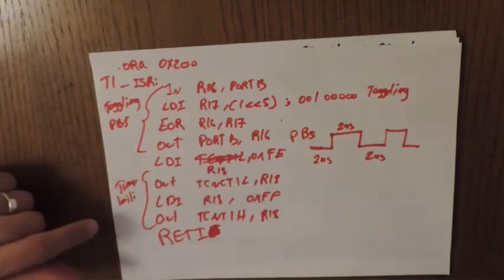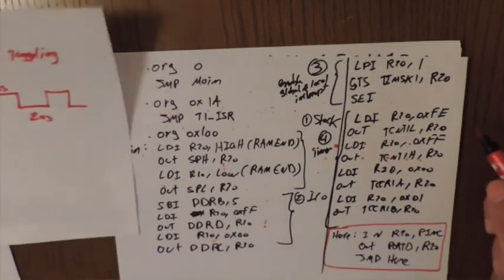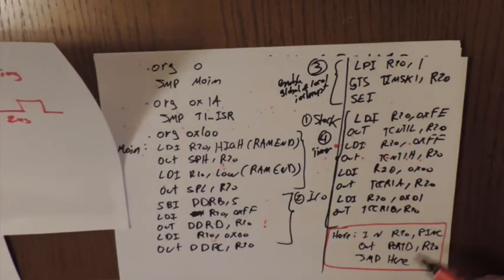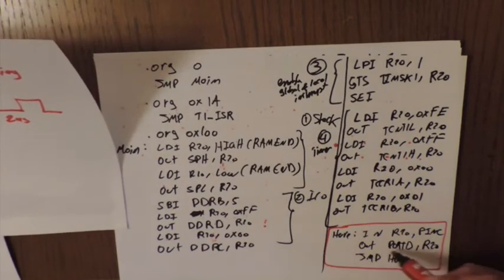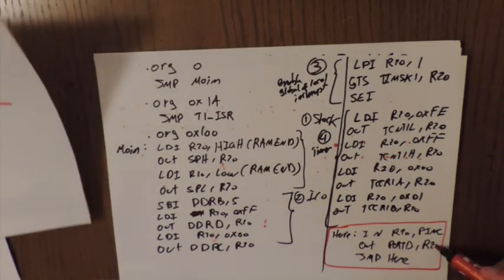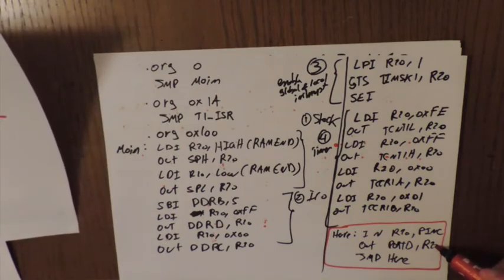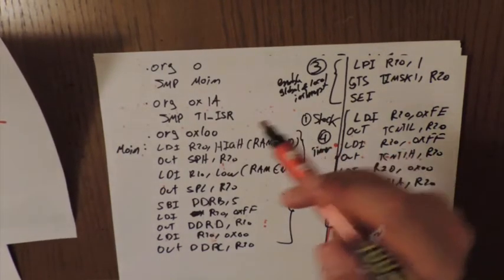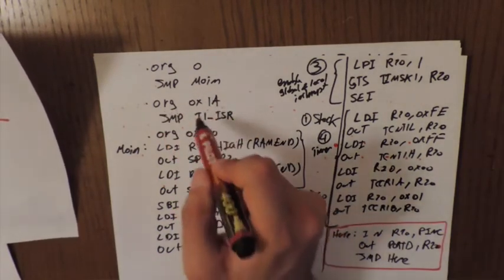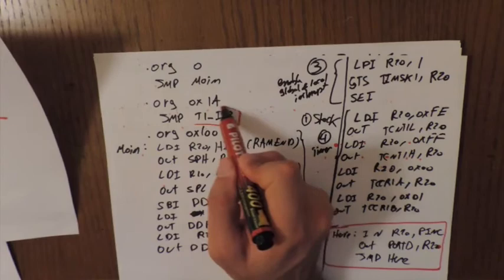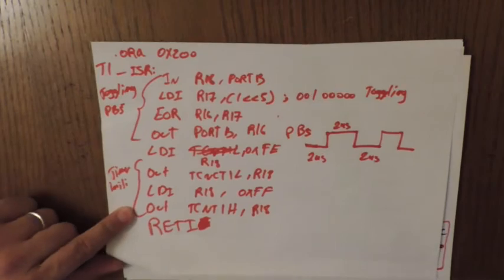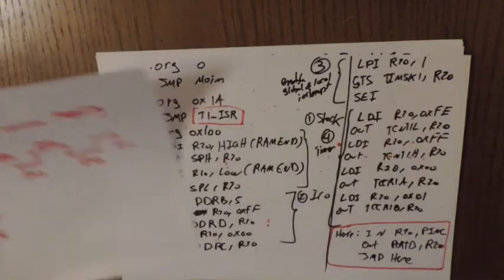And this part is just for timer initialization. Okay, so as I'm copying port C to port D, the interrupt occurs. So I finish executing this instruction. Automatically, since the microcontroller knows that this is a timer 1 interrupt, since I set the interrupt for timer 1, it directs it to 1A. What do we have in 1A? I have the address of timer 1 ISR, which is this one. So I continue on drawing the square wave. Okay, so this is what happens.